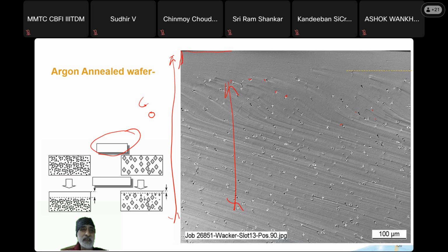It's a 12-inch disc. If it is 3 or 4 microns thin, you cannot handle it, because it would be handled by putting pressure on it. It's very brittle and will break. Another reason is that it has to see temperatures as high as 1200 degrees centigrade. If it is that thin, it will bow and break. So you need mechanical strength to take care of the stresses. Once all operations are done, the remaining thickness will be cut away, and we will get only the top part where the die is.